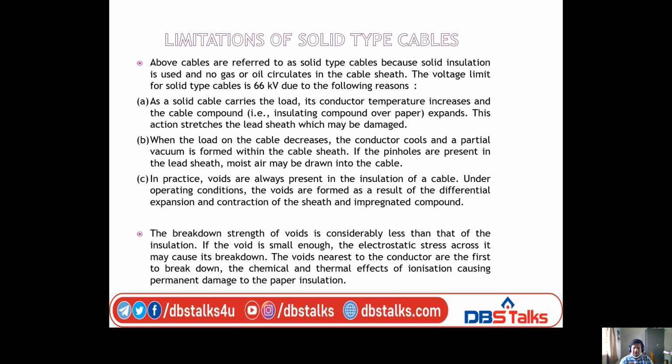So whenever the load is carried, that means current flows, the temperature increases in each and every part of the cable. That may increase the area of cross section. That means the cable may expand. So that may stretch the lead sheath, which may be damaged sometimes.